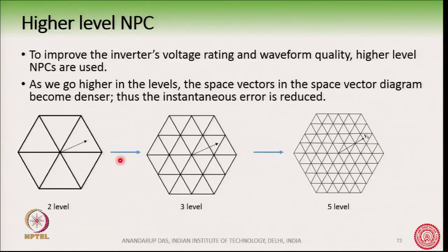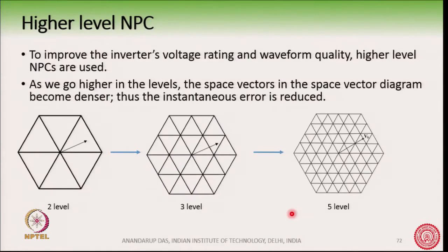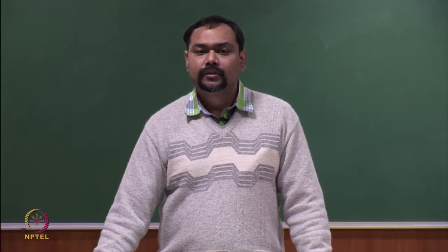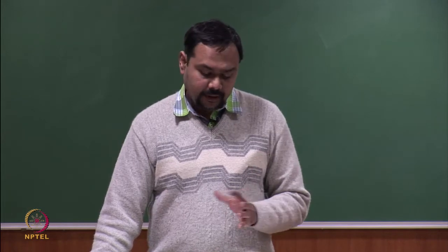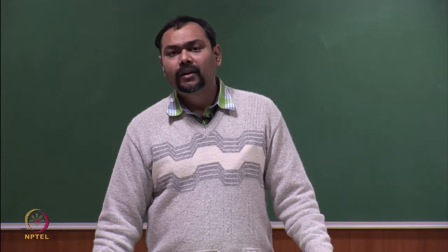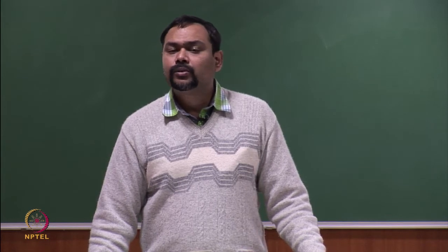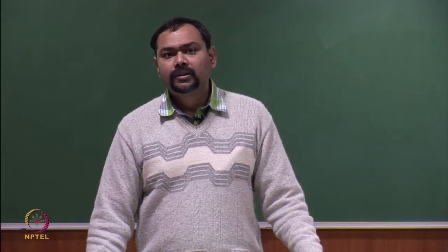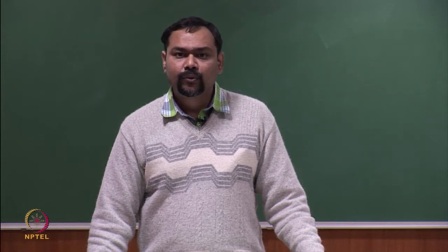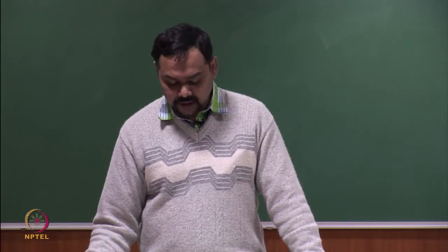We now see the possibility of having higher level NPC based converters. Often, and it has been proposed in the research community, that we can go from a 2 level to, in a conventional NPC, a 3 level NPC. Why do we not go for a higher level NPC? Because it will improve the waveform quality. And of course, it will improve the inverter's voltage rating or the converter's voltage rating.